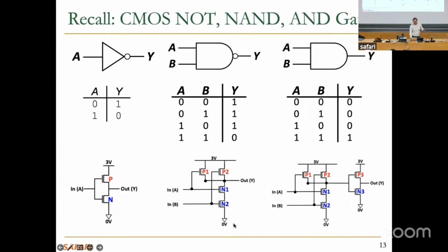And then we built a NAND gate, which essentially is an AND and an inverter behind it, if you think about it that way. And this is the function. We call this the truth table, if you remember. A truth table specifies the operation of a circuit by enumerating all possible combinations of the input. In this case, you have 2 inputs, A and B, which means that each of them can take 2 logical values. So you have 2 to the power of 2 combinations, 4 combinations.